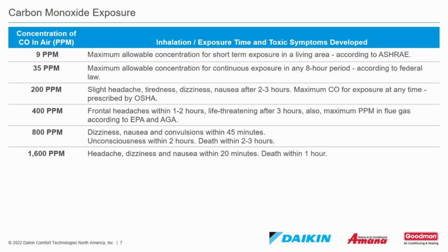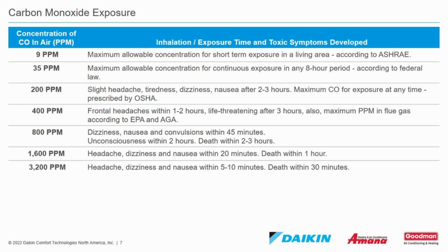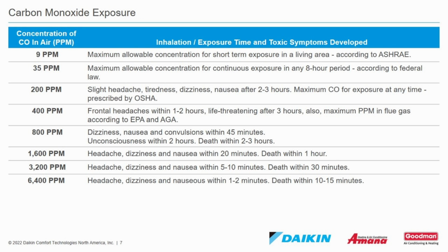1,600 parts per million, headache, dizziness, nausea within 20 minutes, death within 1 hour. 3,200 parts per million, headache, dizziness, and nausea within 5 to 10 minutes, death within 30 minutes. 6,400 parts per million, headache, dizziness, and nausea within 1 to 2 minutes, death within 10 to 15 minutes. 12,800 parts per million, death within 1 to 3 minutes.